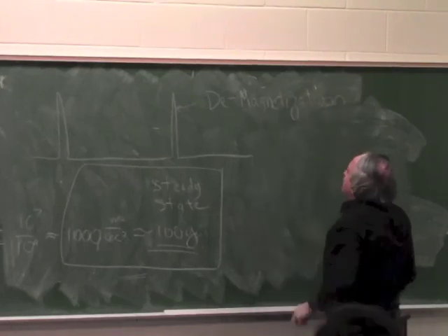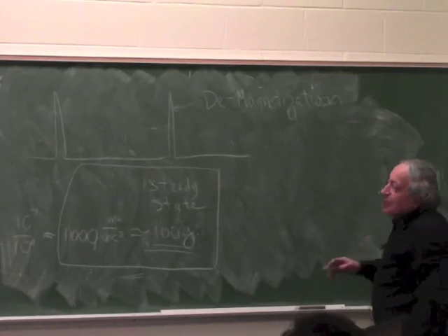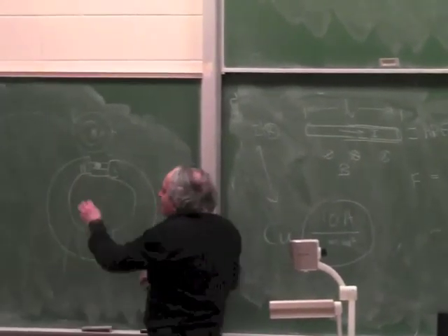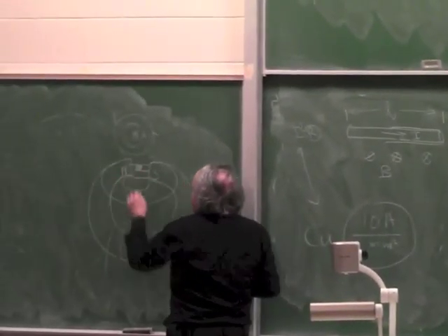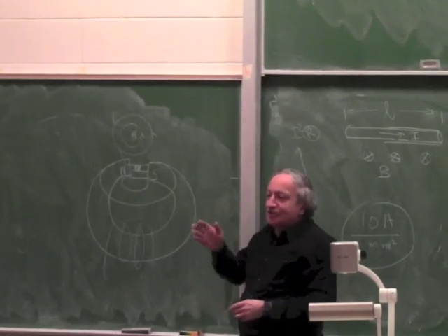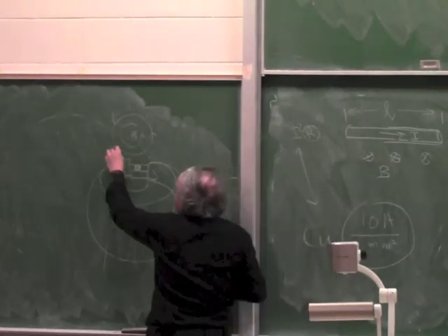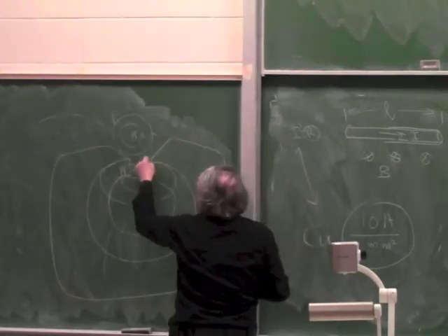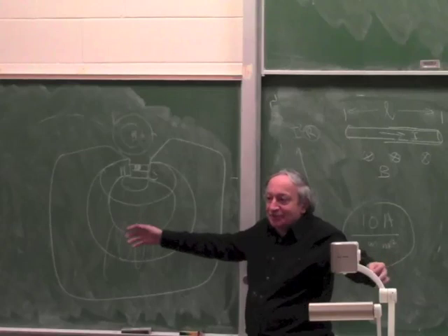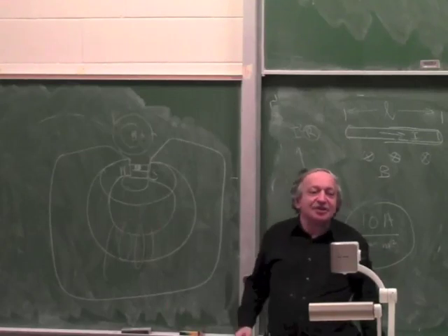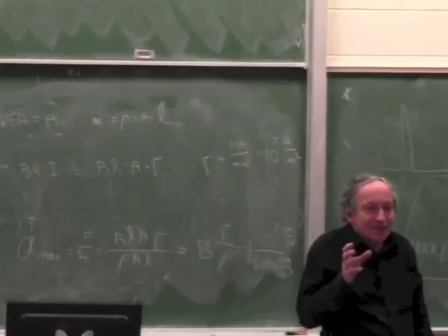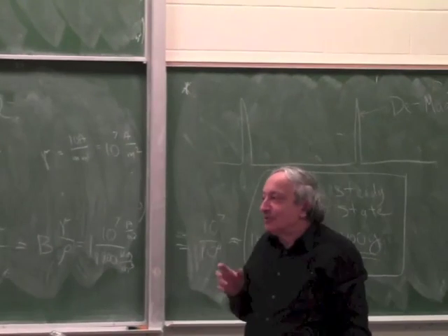And of course here the limit is not a hard number, because you can make this magnet bigger and bigger. So if you want an actuator which works steady state, you can make this magnet quite small, because nothing will demagnetize it. But if you want an actuator which has to work at very fast pulses, at huge acceleration, you can make this magnet huge. So it will be very difficult to demagnetize it. Because this magnet doesn't have to move, so you can make it as big as you want. And that's why on actuators which have to move fast with pulses, sometimes you see a huge magnet. For example, loudspeakers.